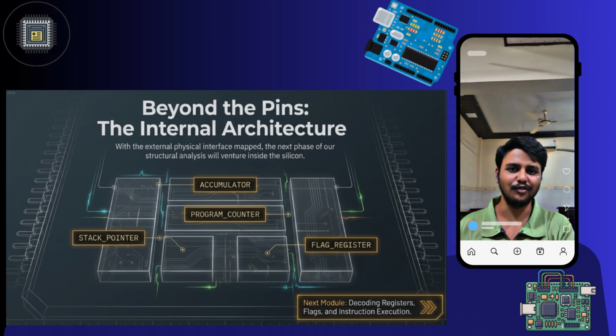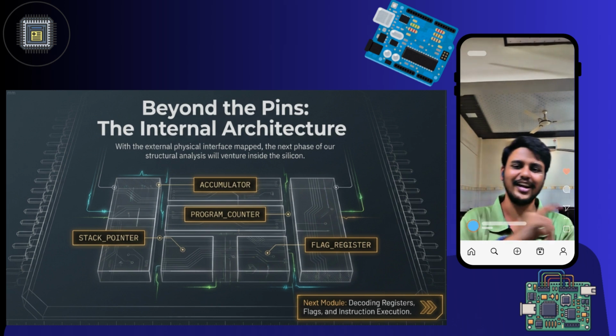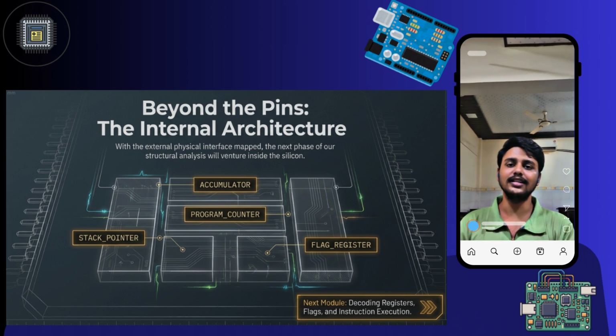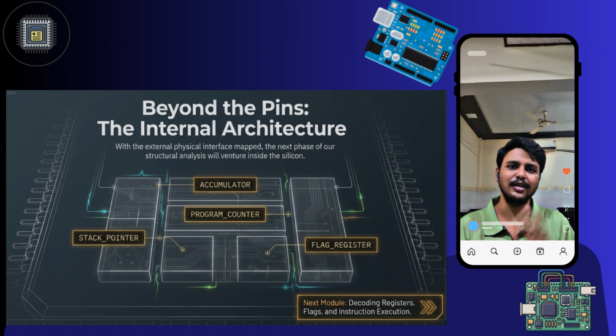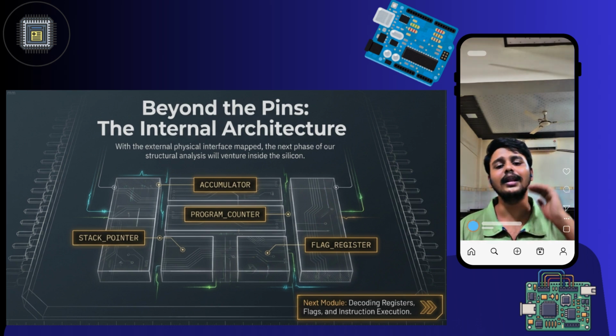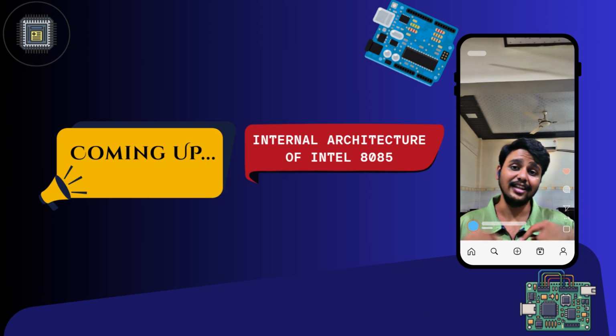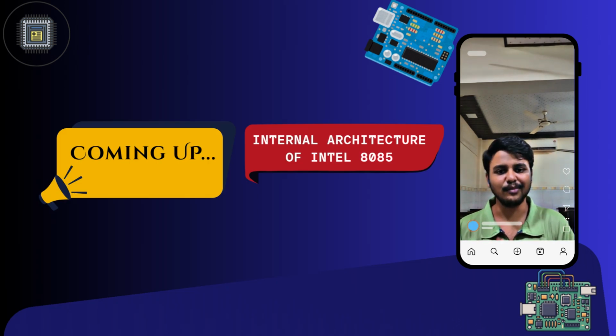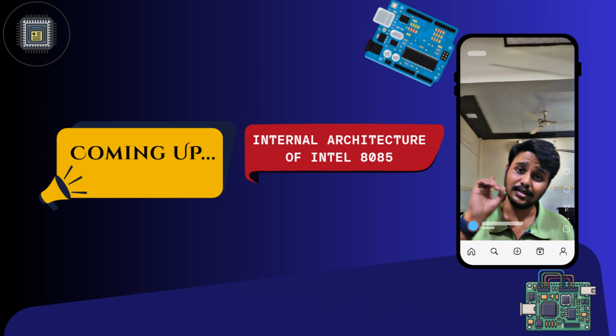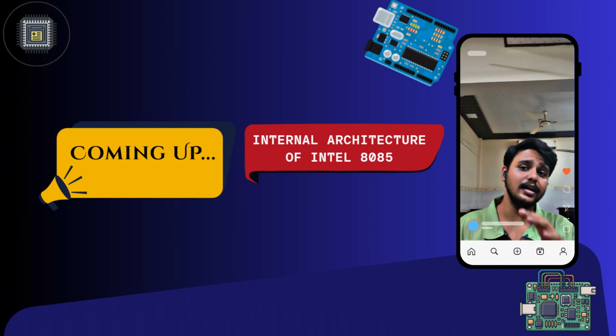Now this brings us to the end of lecture 6, that is the Intel 8085 architecture. Today we introduced the 8085 microprocessor, understood its 8-bit nature, explored the 40-pin architecture configuration, discussed memory addressing capability of 64 KB, examined its power supply requirements and understood how it evolved from the earlier 8080 microprocessor. In tomorrow's lecture, we will go deeper into the registers and flags of the 8085 microprocessor. We will study the register sets, accumulator, program counter, the stack pointer and flags